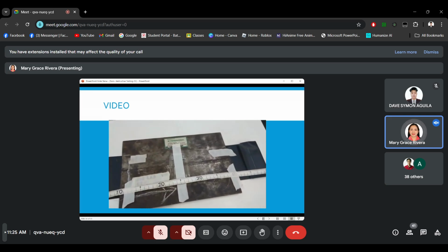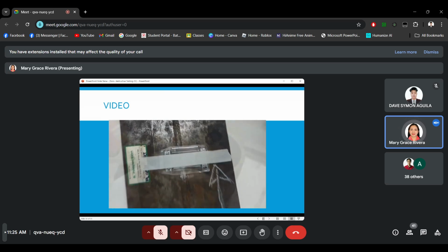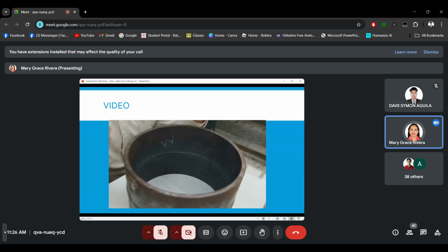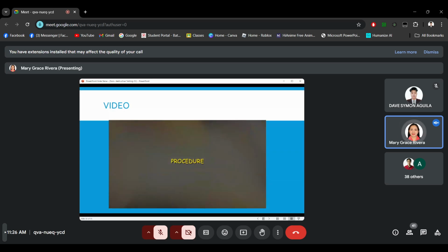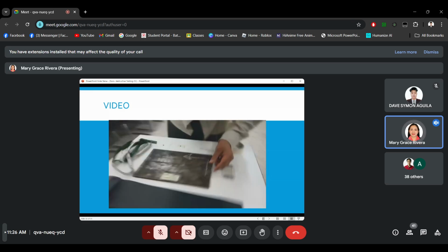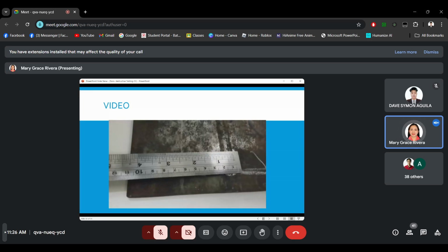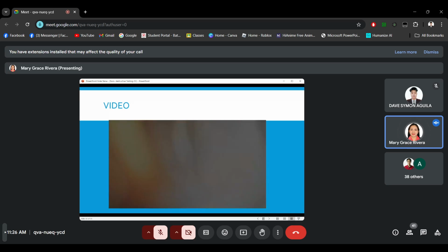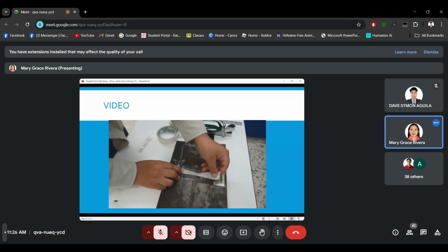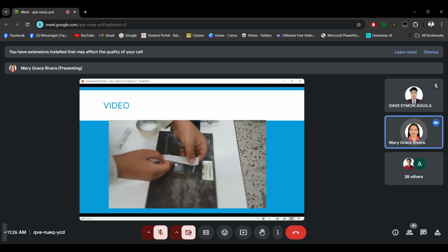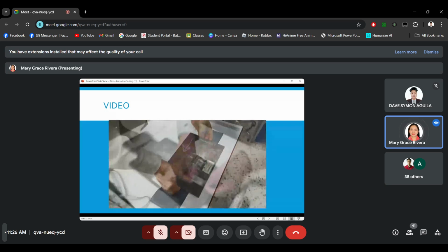First of all, we will show the inspection using the single wall single image technique. This technique is applicable for both plates and pipes, primarily intended for pipes where access is permitted. The procedure is, after finishing film loading, start this technique with a visual inspection of the specimen: examine the welded specimen visually and note down any surface defects. Choose the appropriate IQI type according to the sample thickness, of the same material as the specimen. The IQI should be placed properly on the specimen, that is, on the source side with wires across the weld. Place the film underneath the plate. Place the lead letters.